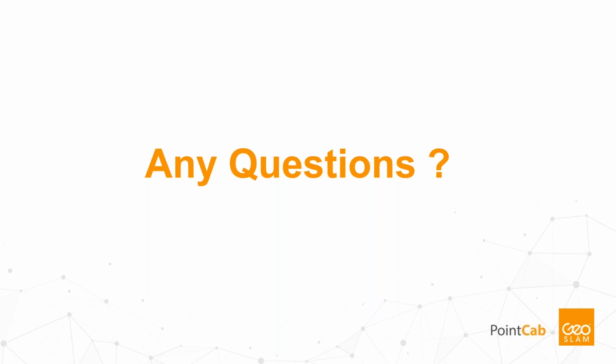Next question. I don't know if you or I shall answer that. The question is: is it better to use reference plates or spheres for referencing? Is one method more accurate than another? So if you use the reference plate, you have very good accuracy with the GeoSLAM device, and you can do it in the field directly, so you don't have to search for the spheres afterwards in the GeoSLAM Draw project.